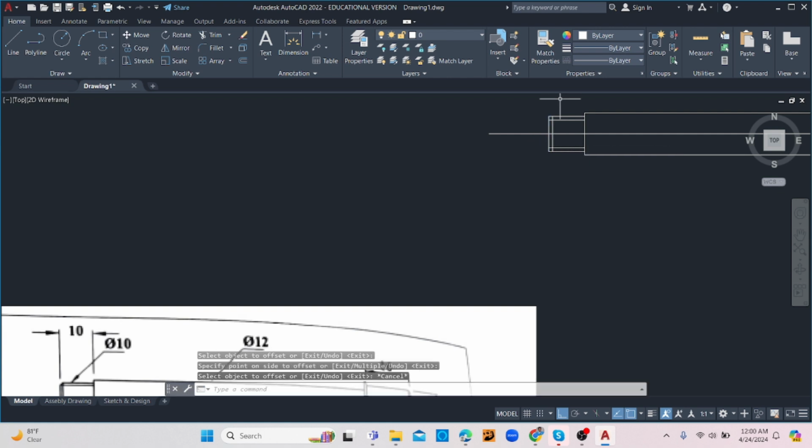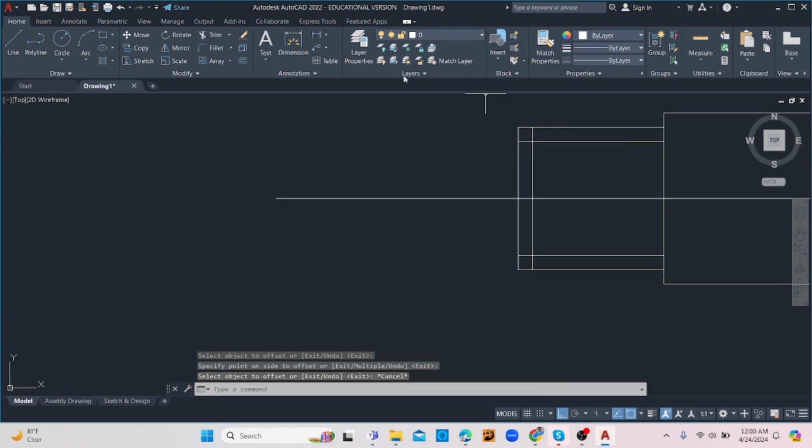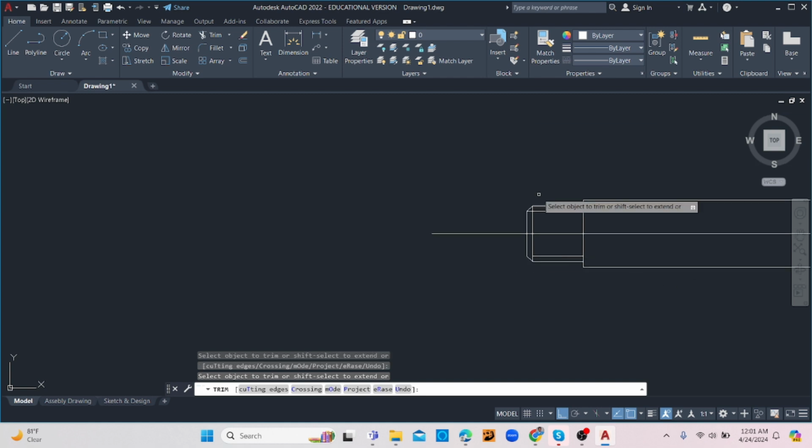You see where those lines are crossing like that? We're going to be chamfering, or you could fillet the corners of that. It's up to you. Alright, you could even draw a line from here across like this as well. Alright, so the option is totally yours. So you could grab onto that, probably delete that, and then do some more cleaning up and get rid of some of these extra lines.